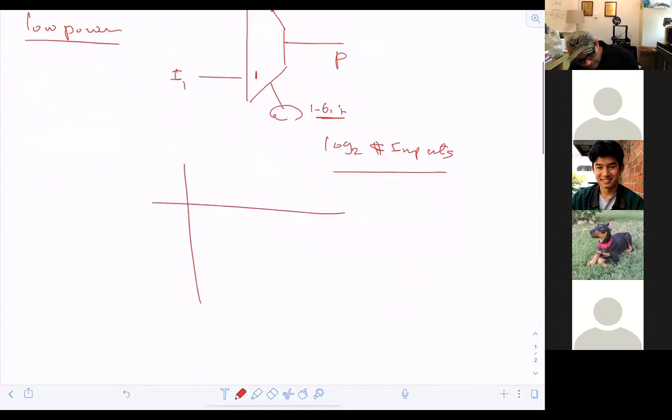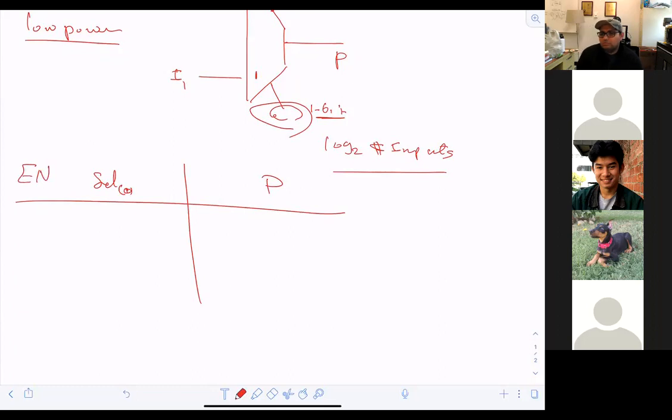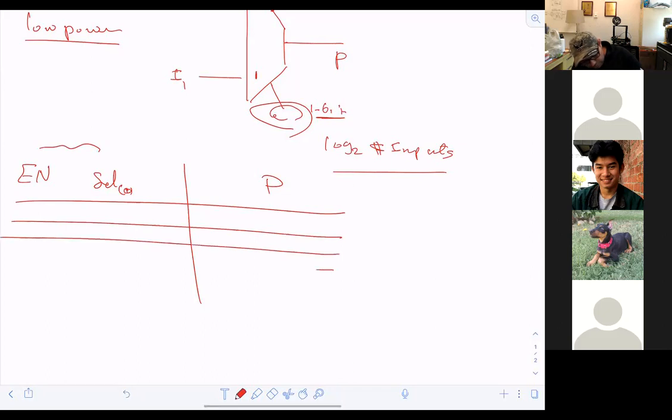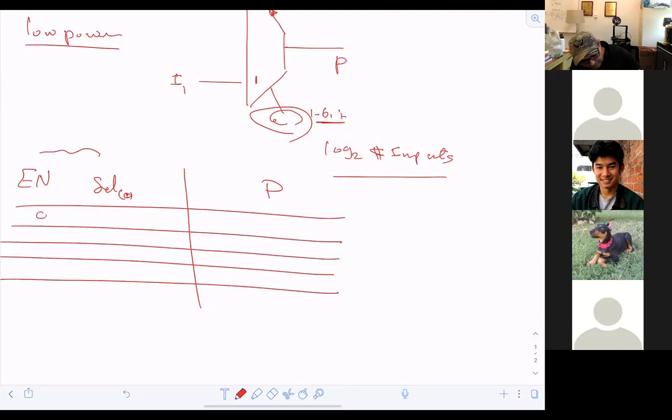Now, if I make a table like this, this is my truth table, right? This truth table has select location 1 or location 0, whatever. I just have 1 bit here, so it's just location 0. And now I have the inputs, but there is an extra signal in my hand called enable, and I'm going to put it here. This table will show the effect of enable with the select for the multiplexer when we go into the gate level implementation of the device. Since I have 2 inputs here, how many states will this table cover? 4, right? So 1, 2, 3, 4. Here is 0, 0, 1, 1. And here is 0, 1, 0, 1.